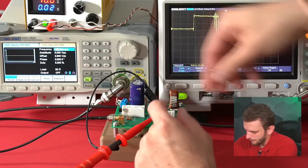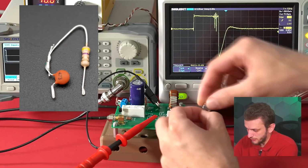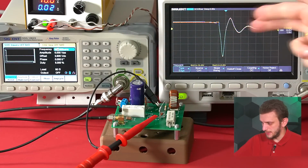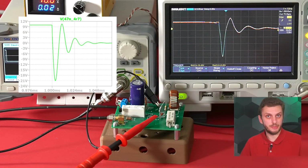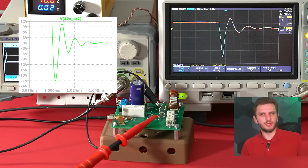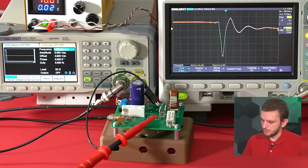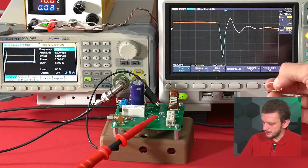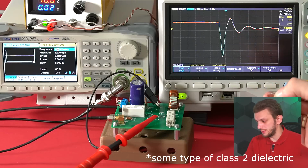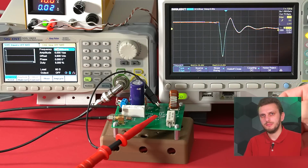Now if we try out a different combination, say the 4.7 ohms and 47 nanofarads, and we rerun the same test. First of all, we can see the oscillation has appeared, as predicted by the simulation, but now our minimum voltage is about minus 31 volts. So here the simulation was telling us something different. And it's important to remember that this is a ceramic capacitor, most likely of X7R type or something similar. When you expose this type of capacitor to high voltages, the value won't stay constant.